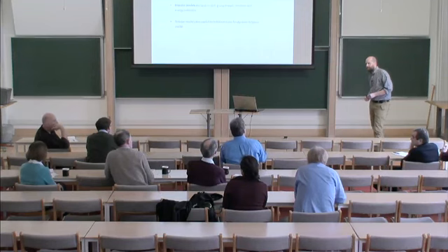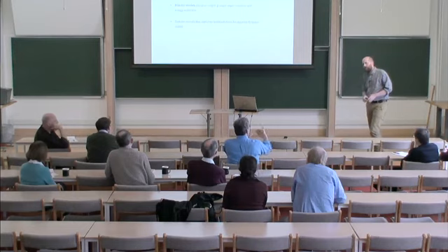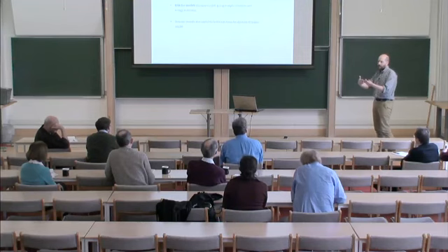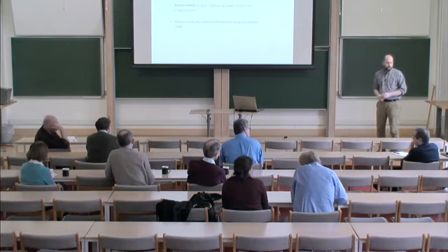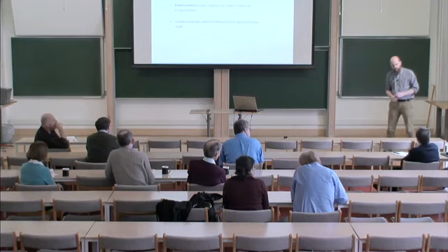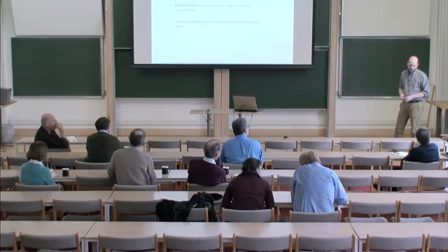In a display like this, do you have an electrode pattern on the back? Is that how it switches? Or do you make a voltage change? Yeah, so all of these displays will have some kind of matrix on the back, or on the front and back, that can essentially apply a voltage to each pixel independently. For your square cavities, don't you need a field that is in the plane of the device?